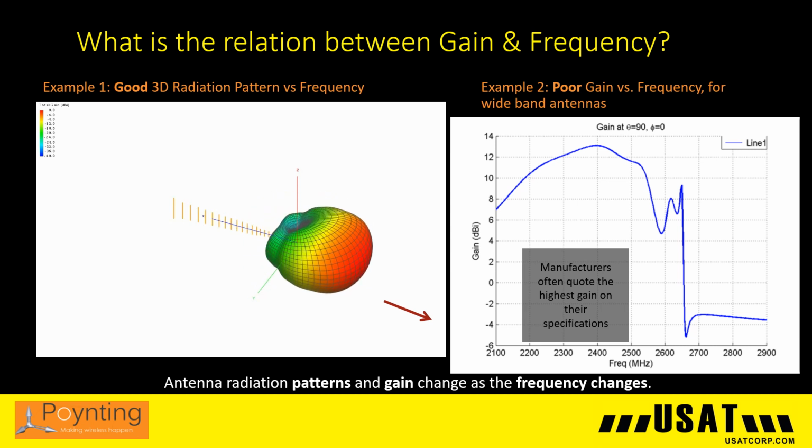A good vendor should fully expose their gain specs over the full frequency range that the antennas could be used in. In addition to gain, the actual radiation pattern of the antenna changes dependent upon frequency. In the case of an Omni, it's not always a ball shape as you see here that shrinks and expands with different frequencies. And you will see visuals of that coming up.